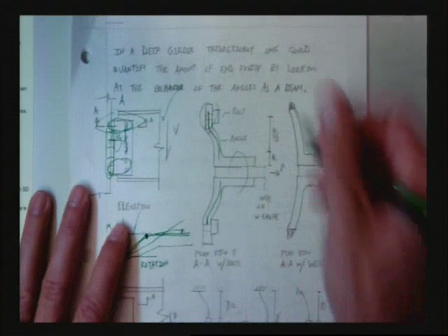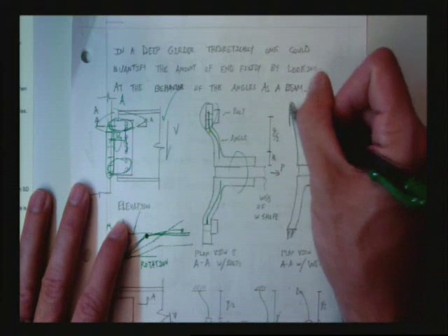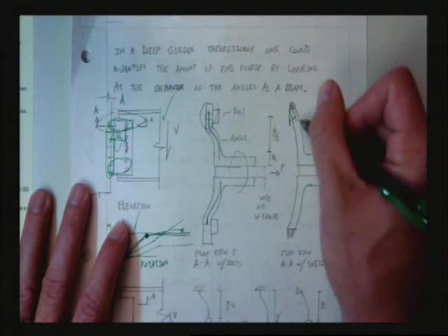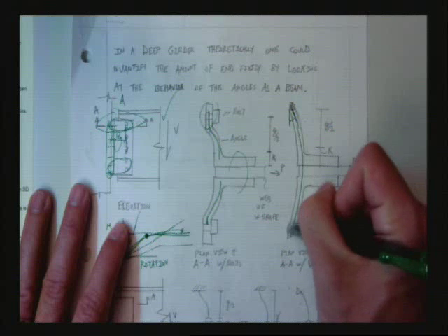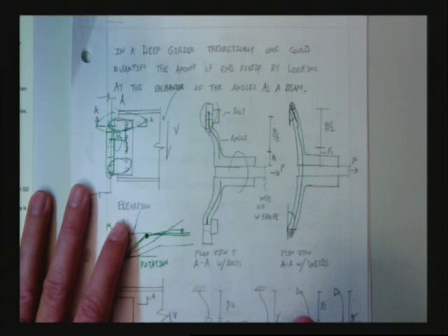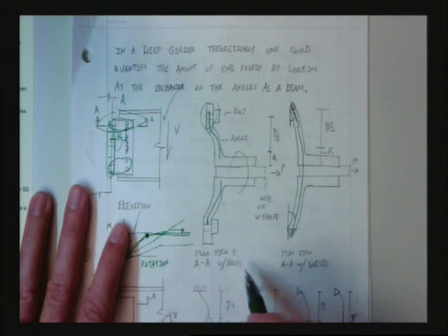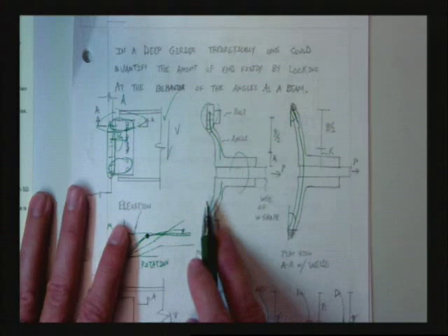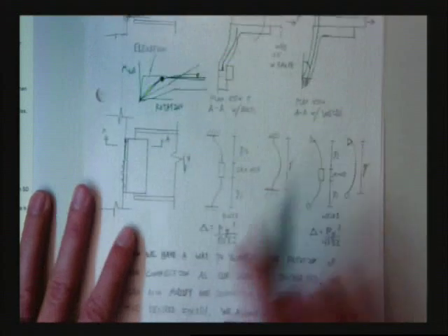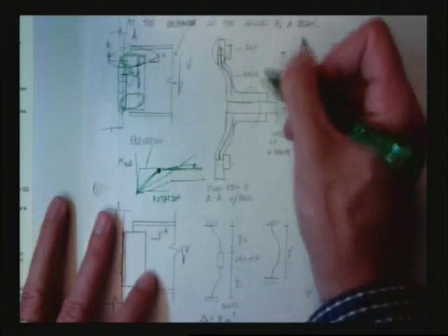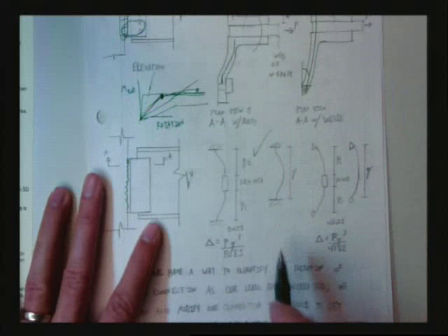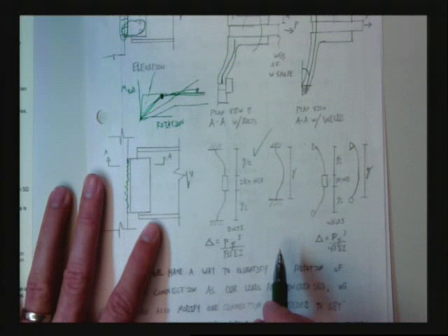And have we ever seen a connection where the rotation, when I say rotation, I mean this rotation, is whatever I want it to be, whatever it wants to be? And it's flat, and it's down here, and it's whatever it wants to be again. We've seen that. And that's a pin connection, isn't it? So if we know how to draw the deflected shape, we know what the critical behavior is, we can actually capture that and come up with a much more simplified model. Being able to go from this to this is worth a lot of money because you can solve a lot of really hard problems.